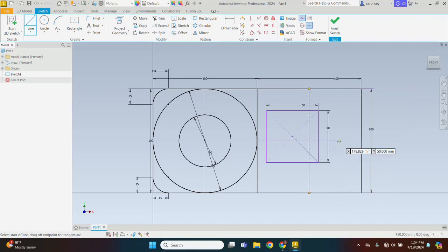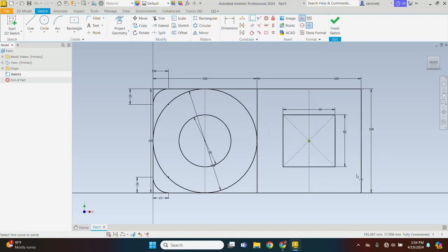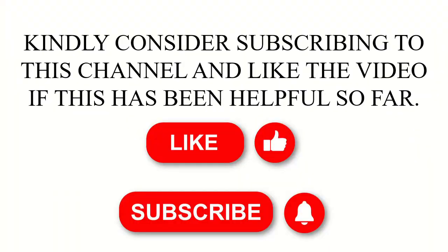You click. You can right click. Okay. Choose the perpendicular constraint and then select this point and that point. That is awesome. And now notice here that the status of our sketch changes to fully constrained.